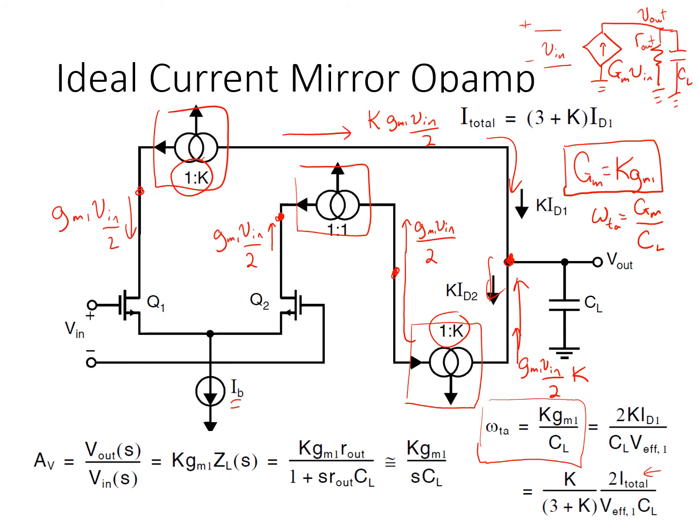And here we're again assuming that the amplifier essentially has a single time constant response, completely dominated by the load cap CL. The picture gets more complicated if we have second poles that limit our unity gain frequency, and we have to compensate the loop to lower the unity gain frequency because of those second poles.